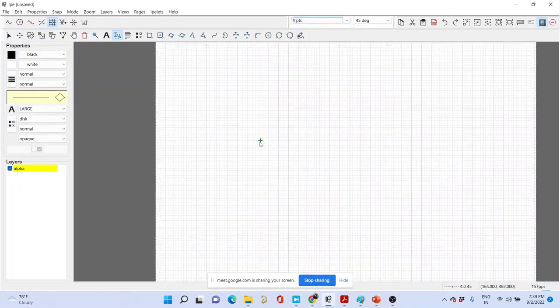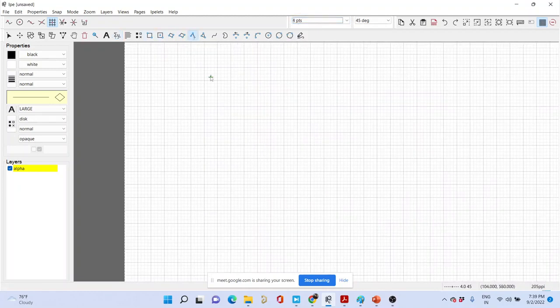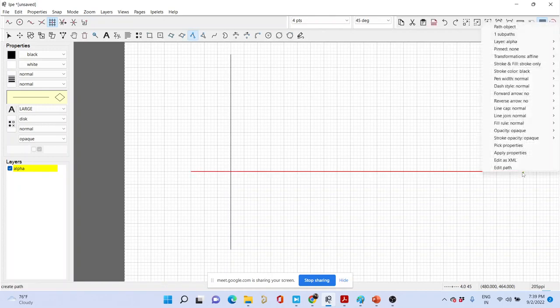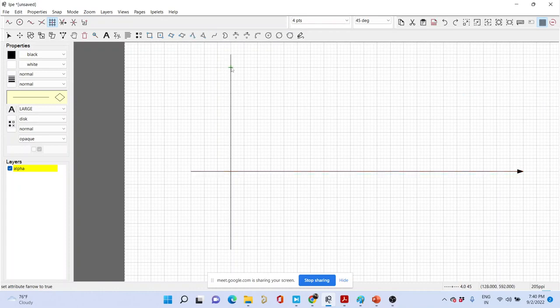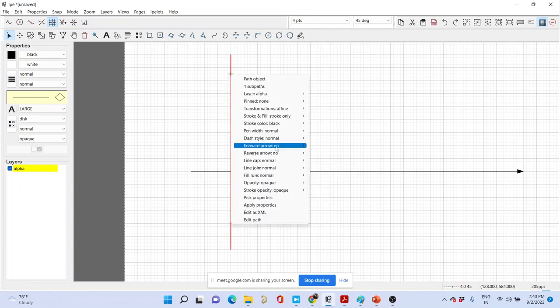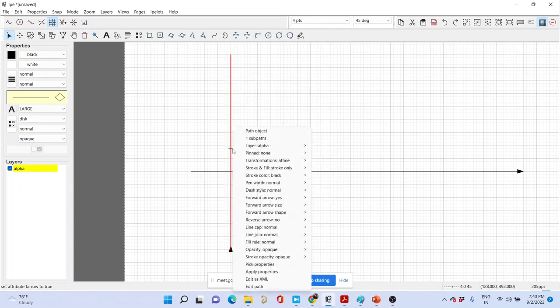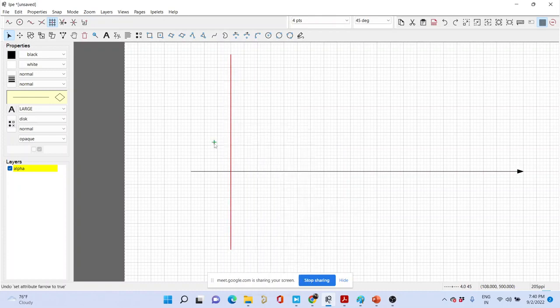So the problem with the PI controller that you would be facing is, let me just draw the axis first. This is the magnitude axis, the 20 log axis, and this is the log omega axis. Say the plant has a Bode magnitude plot like this.